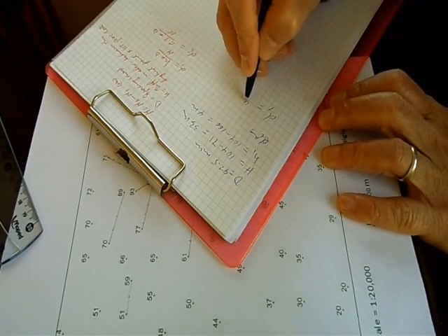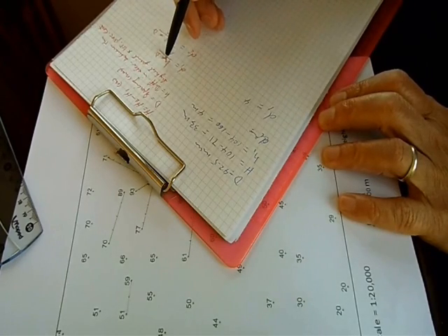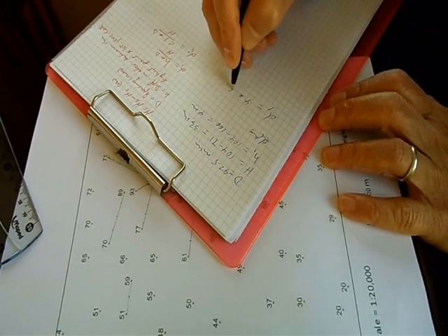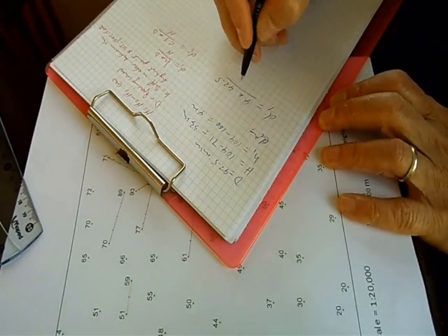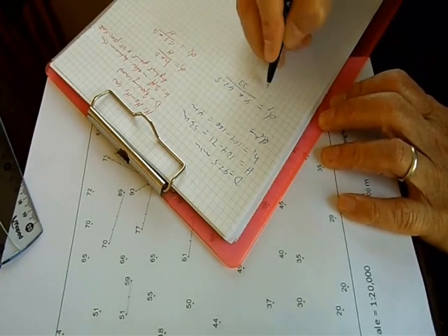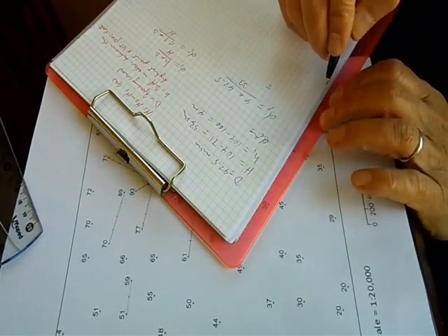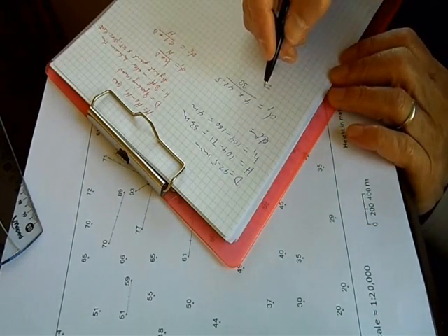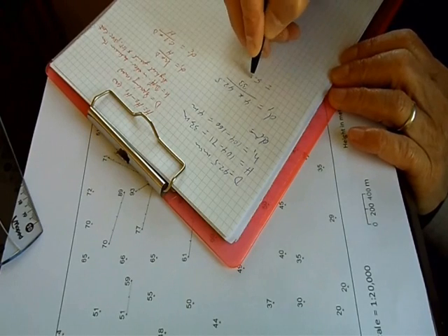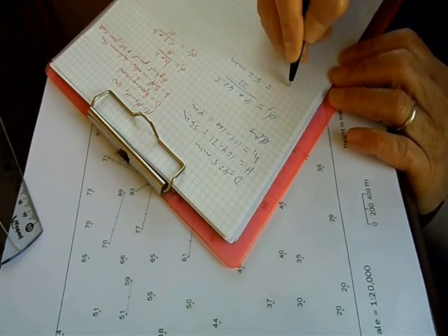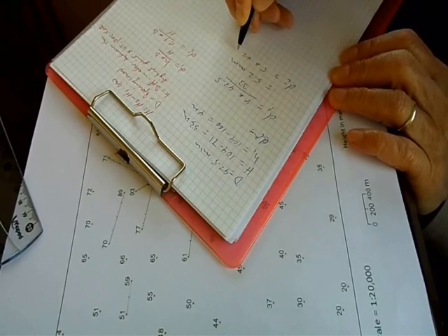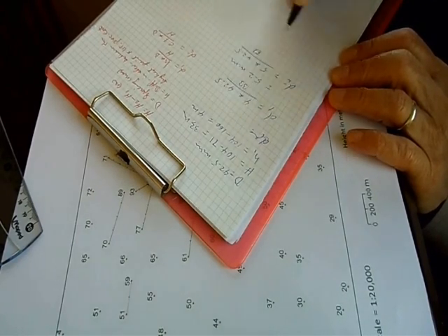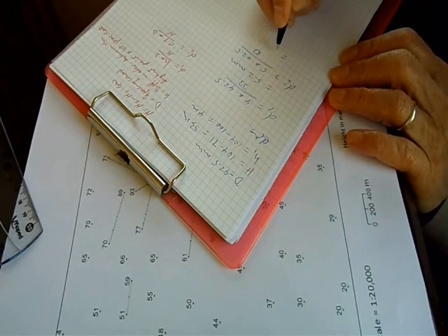Here D1 equals H1, which is 4, times the spacing D, 42.5, over the capital H, which is 33, and this equals 5.15, well, let's say 5.2 millimeters. And Di equals 5 times 42.5 over 33, and that's equal to 6.4 millimeters.